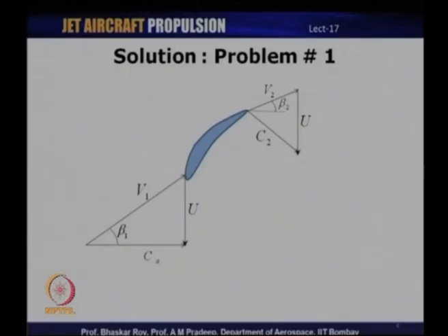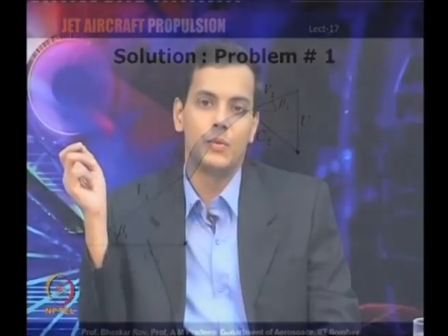So, these are the different components of the velocity triangle, and once we get the velocity triangle, we would also be able to identify which parameters are known. In this case, for example, we know the inlet axial velocity, which is specified, and we know the blade speed, and so based on that we know certain parameters of this velocity triangle. We should now try to solve the problem and find the other components of the velocity triangle, and subsequently we will also need to find other parameters like the pressure ratio and so on, and efficiency. So, let us start to solve this problem.